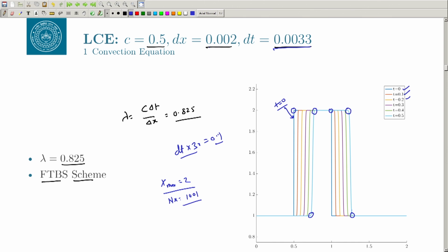And we have to basically estimate what the numerical diffusion in your equation is. That is a very important parameter, especially if you are going for a high accuracy simulation, let us say LES and DNS. If you are using a very dissipative, very diffusive scheme, then it is likely that you will not get a very accurate solution. Things will be very diffused, especially if you have shocks, then you will have a very diffused shock. Instead of a sharp discontinuity, you have the discontinuity over a very long distance, which you do not want.